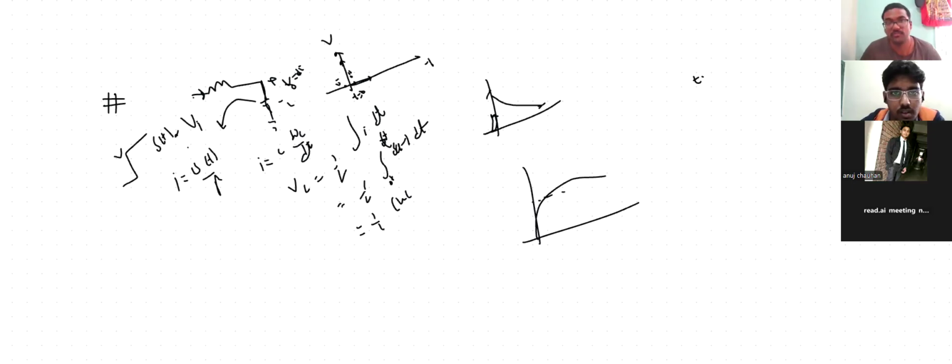I have one small doubt here. If we take impulse and step response at t equal to 0, the frequency component is tending to infinite. That is fine. Because of that infinite frequency, cap is shorting. That is also fine. So when cap is shorting, output is 0 simply. Zero, right, correct. So at t equal to 0, the circuit response is the same. Cap is shorting at t equal to 0. Circuit response is the same: input voltage and output is 0.